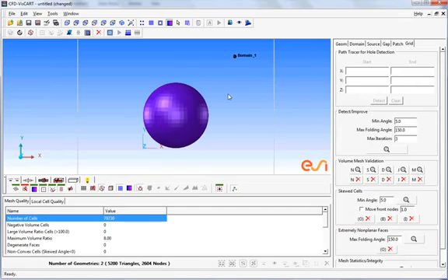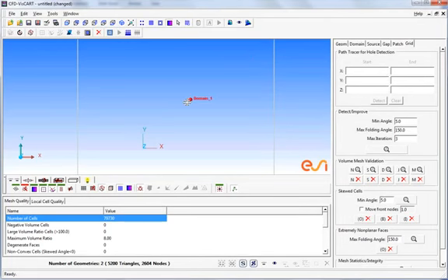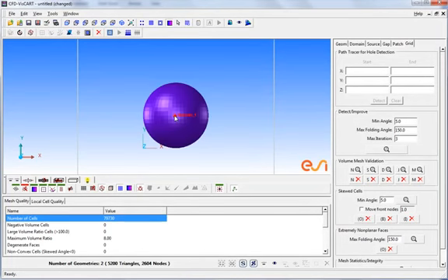Now let us drag the domain marker inside the sphere and regenerate the mesh. In an orthogonal viewing mode, double-click and drag the domain marker towards the center of the model. Switch to another orthogonal view, and double-click and drag the domain marker to the center of the model to make sure it now lies within the inner sphere.